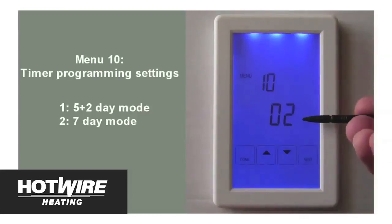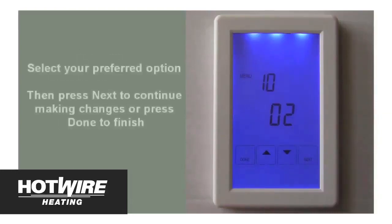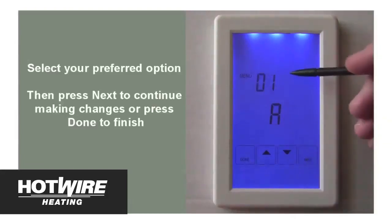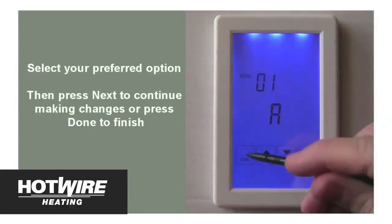Option 2 is called 7-day mode, which will allow you to set the switch on and switch off times for just one day, and they will be applied across the entire week, from Monday right through to Sunday. In this case, we will use option 2, which means we will be given the option to set the switch on and switch off times for one day, and all other days of the week will use these exact same times. With option 2 selected, you can either press Next to go back to the beginning, which is menu 1, or if you're satisfied with the changes you have made, press Done.